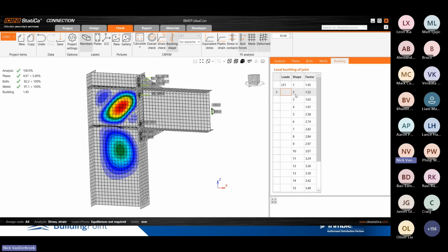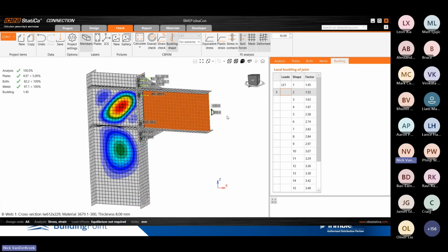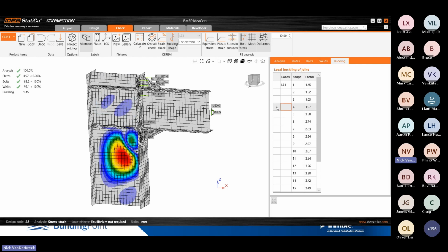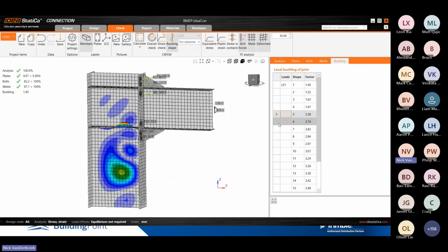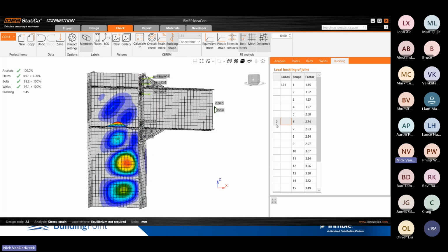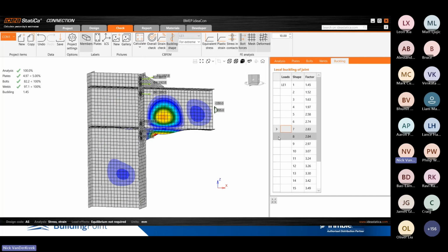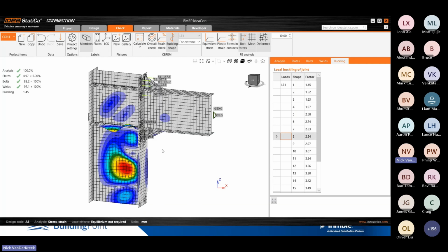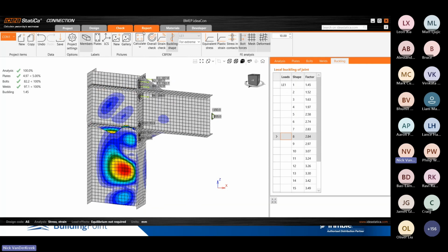And we can proceed through the different modes. We see a shear buckle here. There was an indication that maybe that could be as low as 2. We're less than that anyway, and so on. And clearly we have some issues with this connection. As I say, I've made it deliberately thin and stiffened the buckle there, less than 3. We're still less than 3. So all of these, unless it's well away from the connection, are going to be of concern, I would say. So of course we make the changes and we rerun the buckling analysis and satisfy ourselves, and then at that point we could select the report and so on.